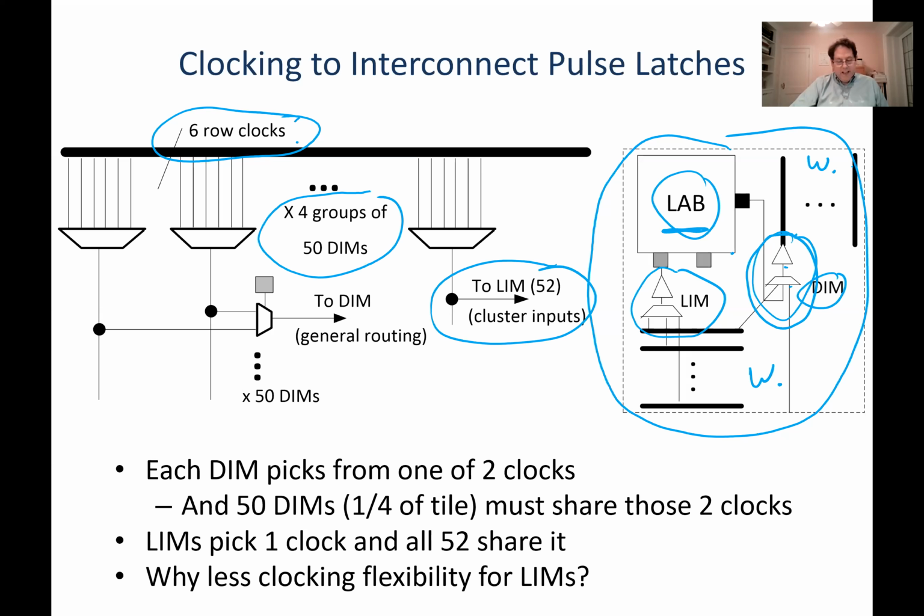Okay, so that's a lot of routing muxes, right? That is 252 different muxes or routing drivers, each of which could now be a register. So they can't afford to build 252 separate muxing networks to choose which of these clocks that are coming by I am going to use. They couldn't build 252 6-to-1 muxes. It's just too expensive. So what they do instead is they basically